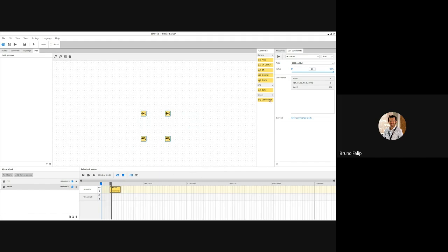I wanted a warm color, so let's select color, which is a DT8 feature. Click here, for example. Same, we need to select broadcast, and within the DALI command, I'll have to select not RGB but temperature, because I know that my device is working with temperature. So this is something a bit crazy with DALI.